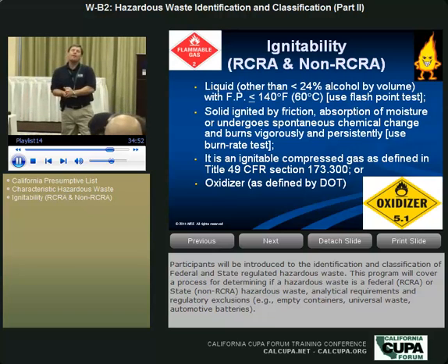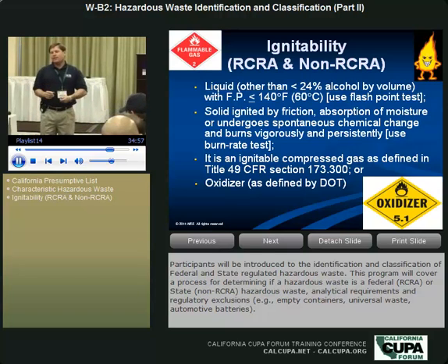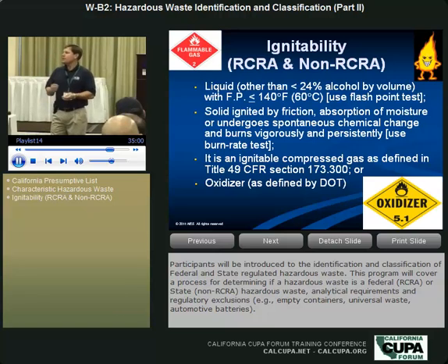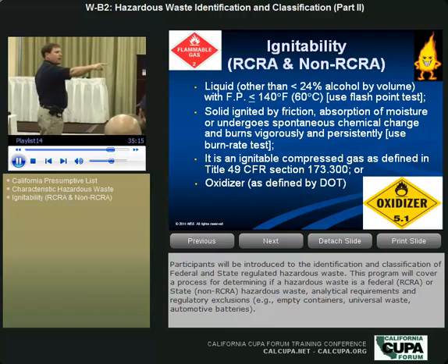The problem I've seen historically on this particular issue is that it's treatment. You're engaged in treatment. Not deliberately, but you are. You're treating the waste. You're changing the chemical composition of the waste. The container's closed and it's open, it's closed and it's open, it's closed. And then over time, unless it's sealed, like DOT requires it to be airtight, this container's closed, not sealed. This container's closed and sealed. But if it's open and closed to atmospheric pressure on and off periodically, those VOCs are going to off-gas. They're going to evaporate.